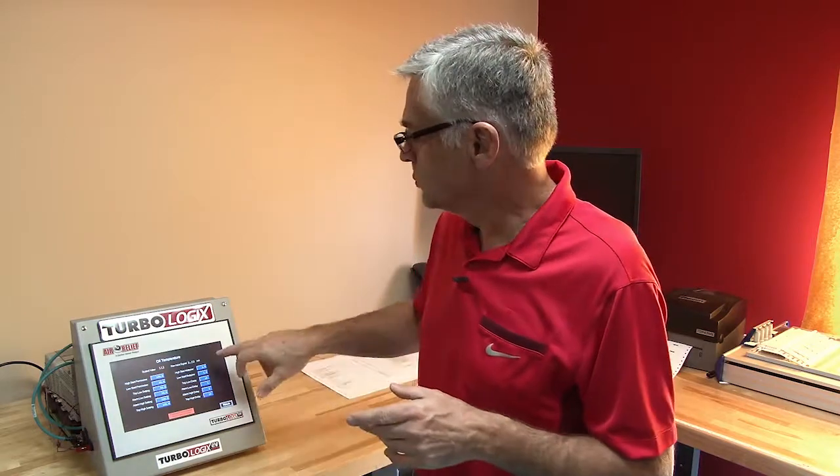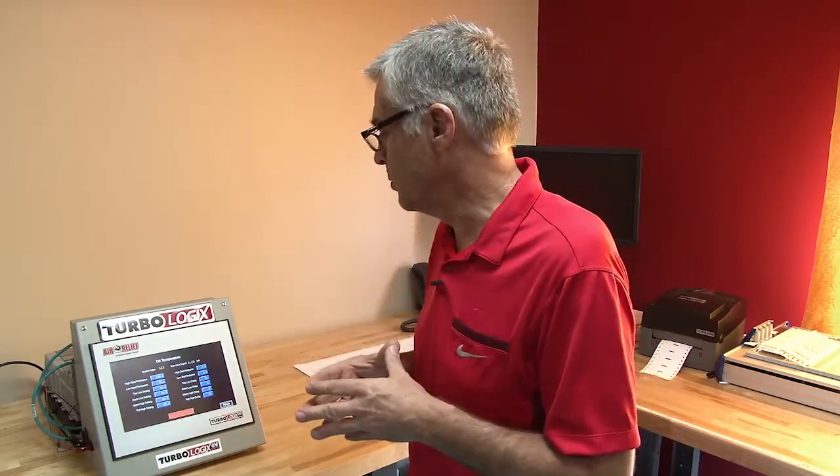Not every input needs a low trip setting. For example, interstage air temperature more than likely will not have a low trip setting. However, oil temperature will. And you can also set, of course, the high alarm and trip values, trip multipliers, and then we also have delays on here so that if a temperature goes out of tolerance slightly and then maybe goes back in tolerance, you don't just get an immediate trip or a shutdown. You can delay that trip or alarm for a few moments.